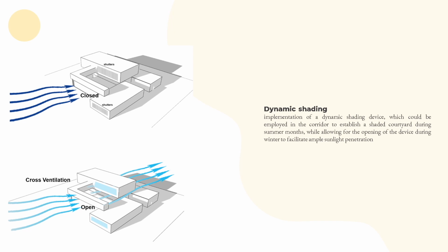The figure highlights that the design of the house has been thoughtfully developed for optimal natural ventilation by integrating operable windows and vents. Windows have been positioned toward the south, while open courtyards facilitate the entry of refreshing breeze into the house, enhancing the overall cooling effect in summer. While in winter, the courtyard is enclosed by movable louvers, providing protection from cold winds and minimizing the heat loss. And the intentional design adjustment helps to maintain a cozy, warm living environment during cooler periods.